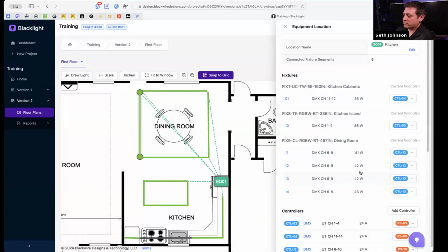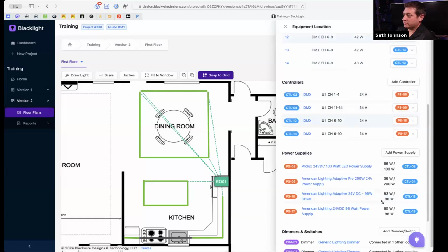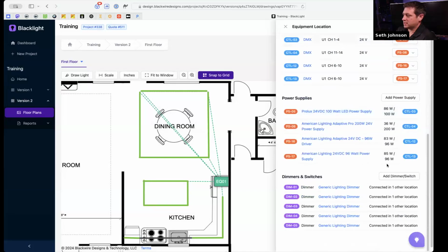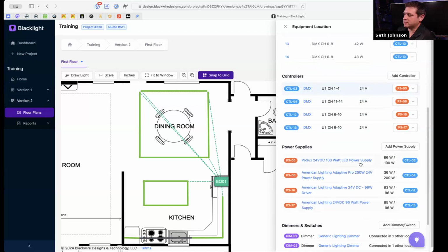And we will have a warning for that 24 volt 96 watt in the future. Like this one here would start throwing some errors, maybe this one too. Anything that's going to have a non-class 2 power supply, you may want to be made aware of that so you can make different decisions in the future.